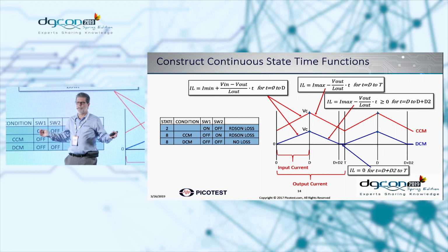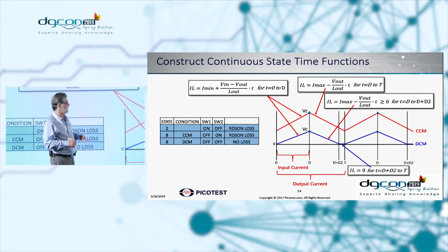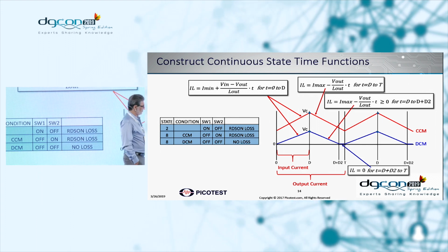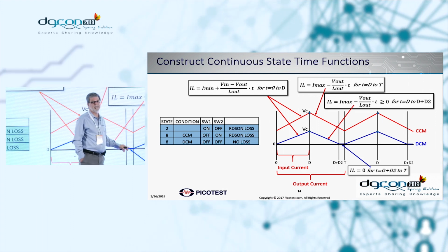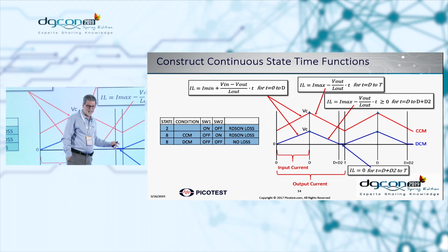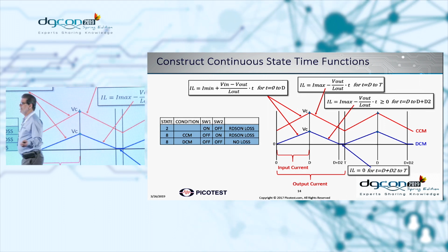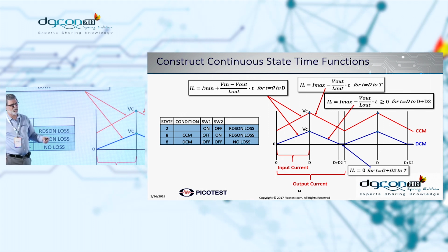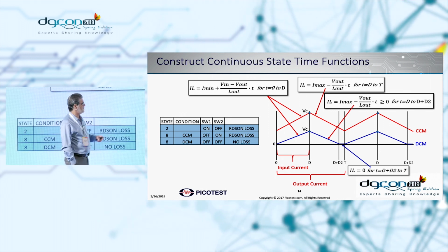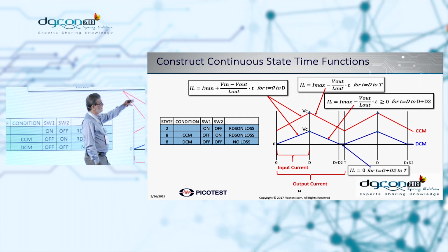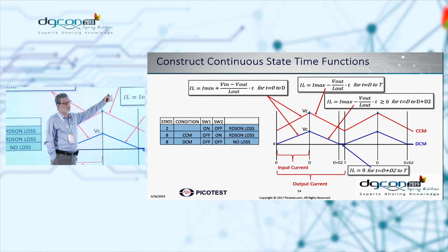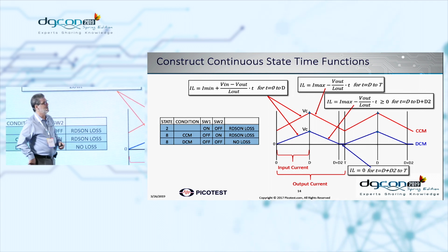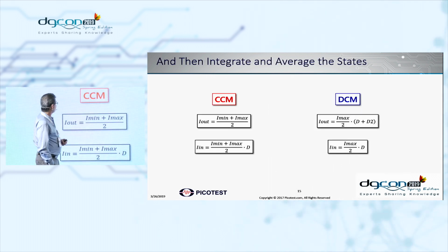And so we know what the voltage is across the inductor at any time, and that means we can integrate these. If the current does fall to 0, then it is in discontinuous conduction mode, and it's going to sit there at 0 until the next cycle starts. So we can actually reconstruct what the current waveforms look like in this inductor during a cycle. And I can write the equations for those, and those are linear equations. So we have now linearized the entire operation of the switching regulator.